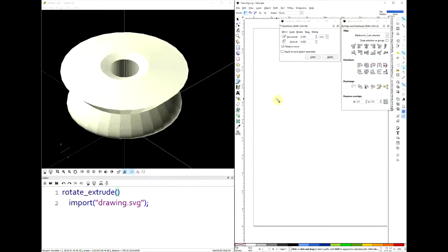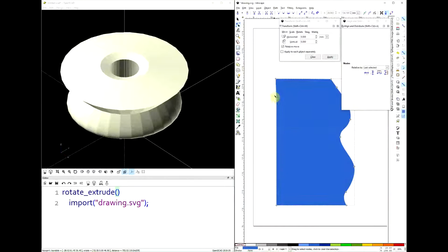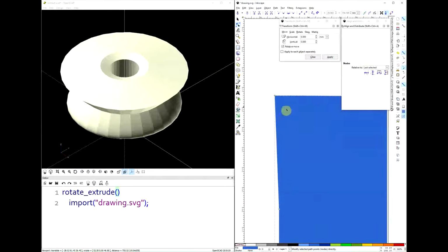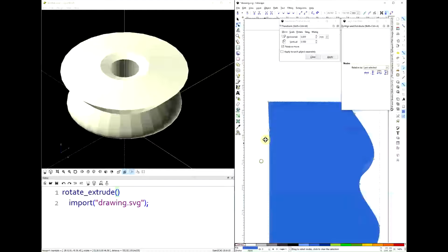I'm going to hold down my control key so that the nodes fall on an X or Y axis. So that's what I have so far. And then over here I can just put some curves in however I like, clicking and dragging. And then I'm going to do a solid one and end it off over here. Now if I go to the node editing mode here, F2, you can see that these two nodes, this one and the top corner one, don't have the same X value. They're not directly above and below each other. That'll cause problems if I leave it that way.